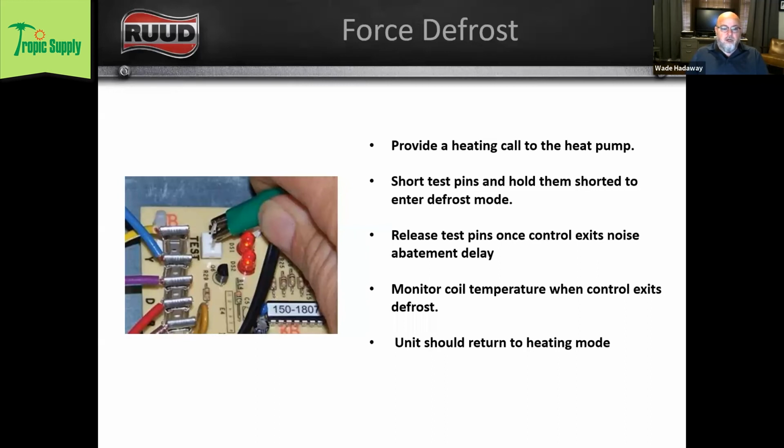So you're going to short those test pins. It's going to speed everything up. So that 30 seconds is not going to last 30 seconds, because when you're forcing it into defrost by shorting the pins together, it sort of fast forwards that logic. So once it comes out of that sound abatement delay, you can release the test pins, or you can move your screwdriver or your alligator clips.